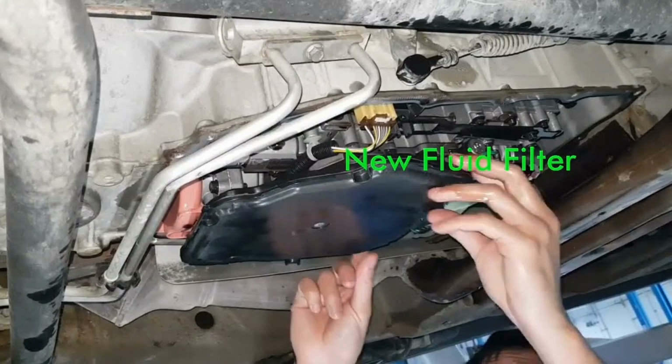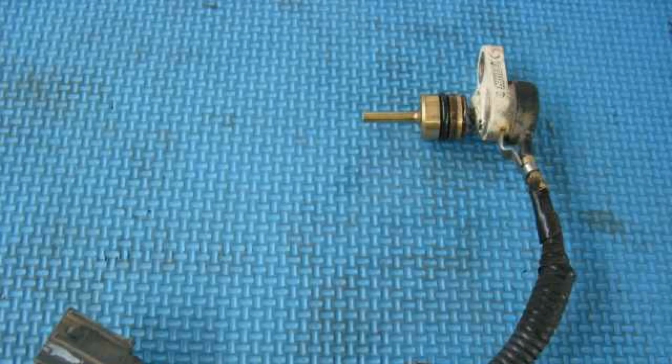Diagnosis of code P0711. Accurate diagnosis of code P0711 is crucial to identifying the underlying cause of the problem and undertaking the appropriate repairs. Several diagnostic steps can be followed to establish an effective course of action. Using an OBDII diagnostic scanner, visual inspection of wiring and connections. A visual inspection of the wiring and connections associated with the transmission temperature sensor is crucial.